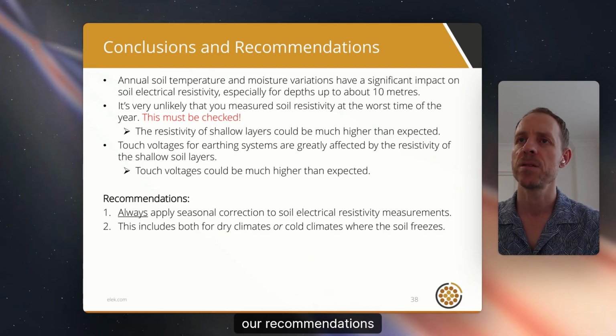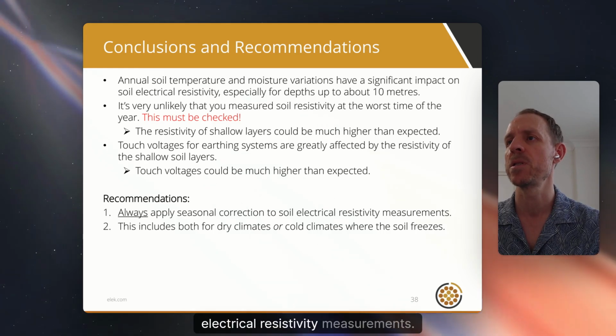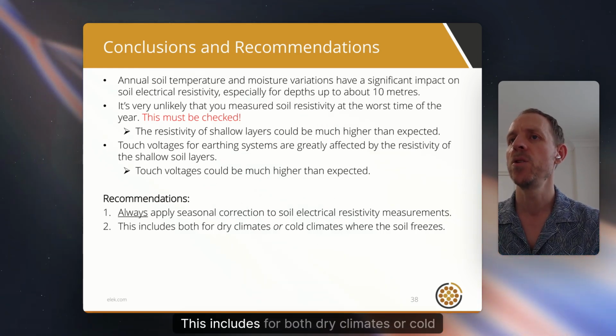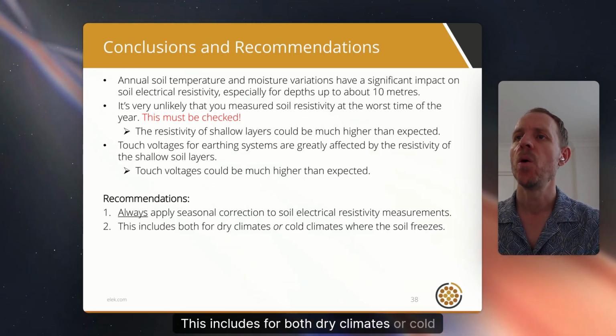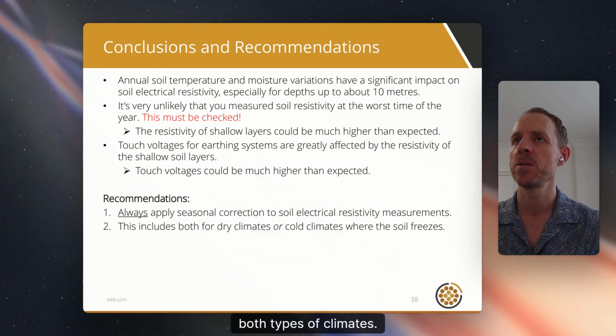Finally, recommendations. Always apply seasonal correction to soil electrical resistivity measurements. This includes for both dry climates or cold climates where the soil freezes, both types of climates.